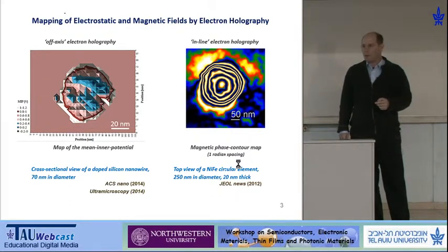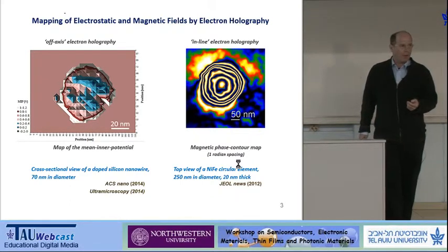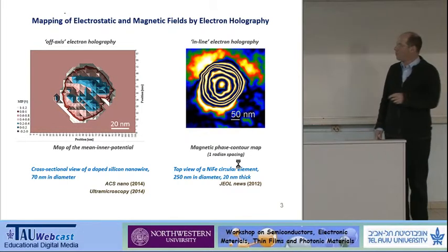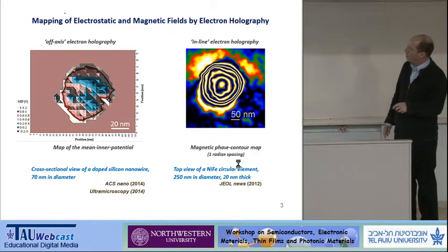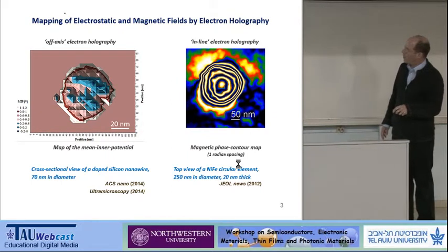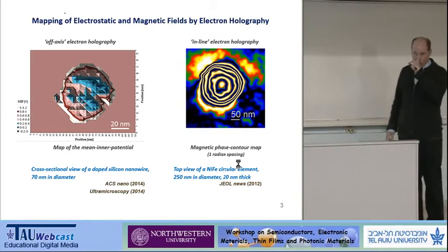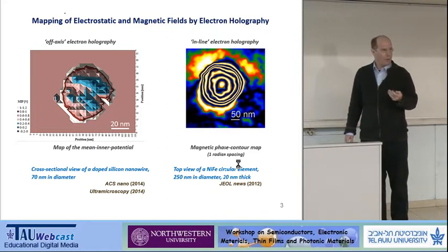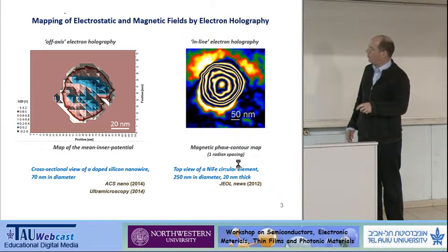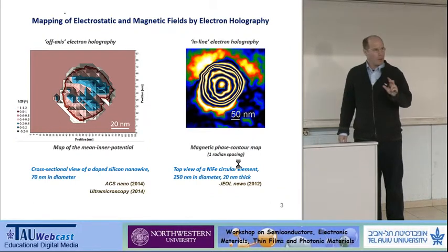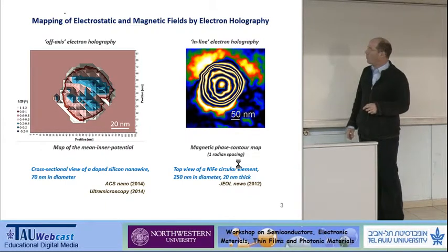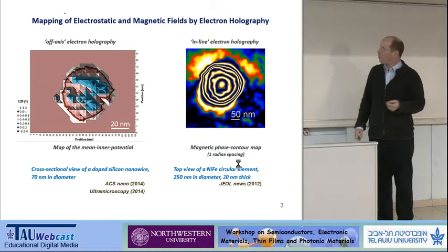Basically what it does is map the electrostatic potential in your material. In the case of a semiconductor, the variations in potential follow the band structure. So if you have something like silicon, this color code shows the change of the potential along a scale of about 1 volt. That's just the gap of silicon. It's quite highly doped, what Roy is doing. So you can see a proof of the kind of vertical doping he was aiming for. But the same approach can be done for magnetic components.